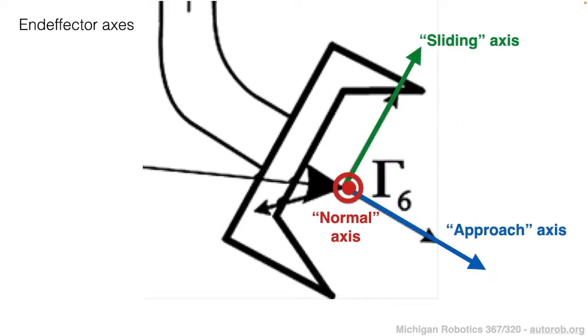And so typically when we think about these end effector axes, the way we can think about it is that they'll sort of align with the actual tool that the robot has access to. So in the case of a gripper tool, the actual axis of this gripper tool would be defined, for example, with respect to where that gripper action can take place. And so then using knowledge of where this end effector axis is within the world is what will ground our actions that are made using the tool of the robot, right? So in the case of the gripper, if you know where this end effector axis is, then you know exactly what closing the gripper at its current position would result in for task planning within our robot.